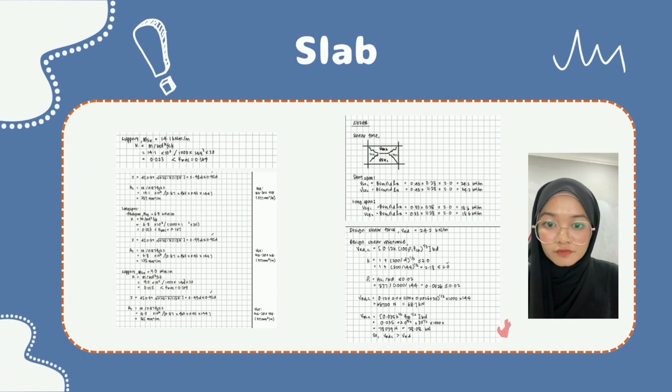I calculate the support for the main reinforcement. So my K I got 0.023, so I use the 0.023 because it's below the K bar 0.167. Then I calculate the Z, I got 0.98D again, so I use the 0.95D. Then I got the AS for the support 257 mm square per meter. Then I use the H12-300 for the top, so 377 mm square per meter. I use the same bar like the support and the midspan.